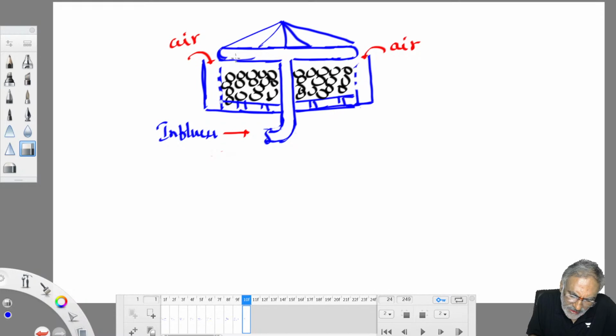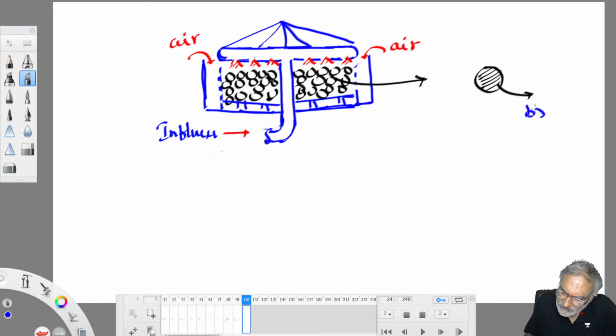Here this contains small nozzles through which we apply wastewater at the top of the media. So wastewater trickles down like this. This is wastewater. On the surface of the media, if you see, there is a broken brick or broken stone. This is inert media. This is used as inert media.